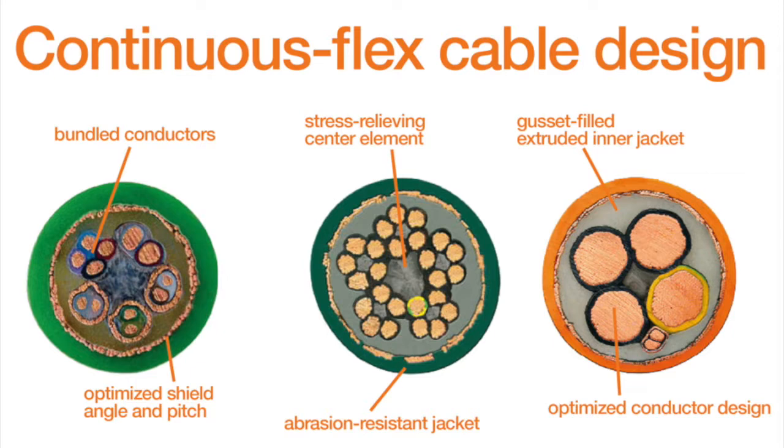And in a layered cable, a lot of times manufacturers use the loose tube extrusion simply because it's a cheaper method of making the cable. While that may work for a flexible or a static application, it's certainly not optimal for a continuous flexing application. And the final design point we have is the optimized conductor design. That is when we look at the actual thickness of the material, of the copper conductor itself.